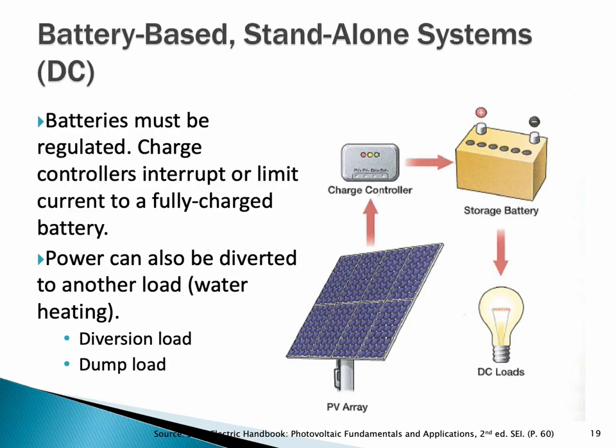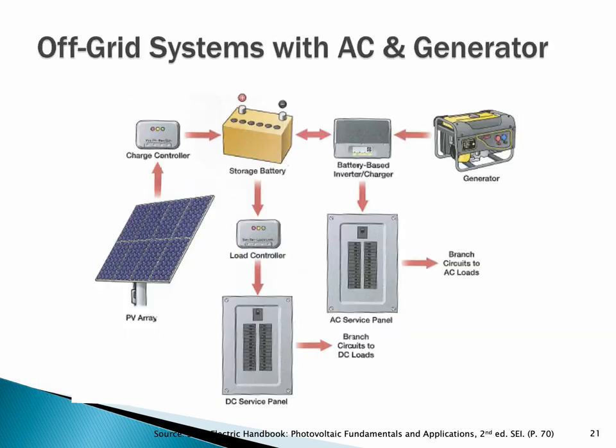That's a DC-based system, has a single panel, a charge controller, a lithium battery, and a DC load, the speed sign and electronics. So there is no inverter on that system. In this neck of the woods, if we have an off-grid system, we need to have a generator to get through the low sun hour months, December, January, February.